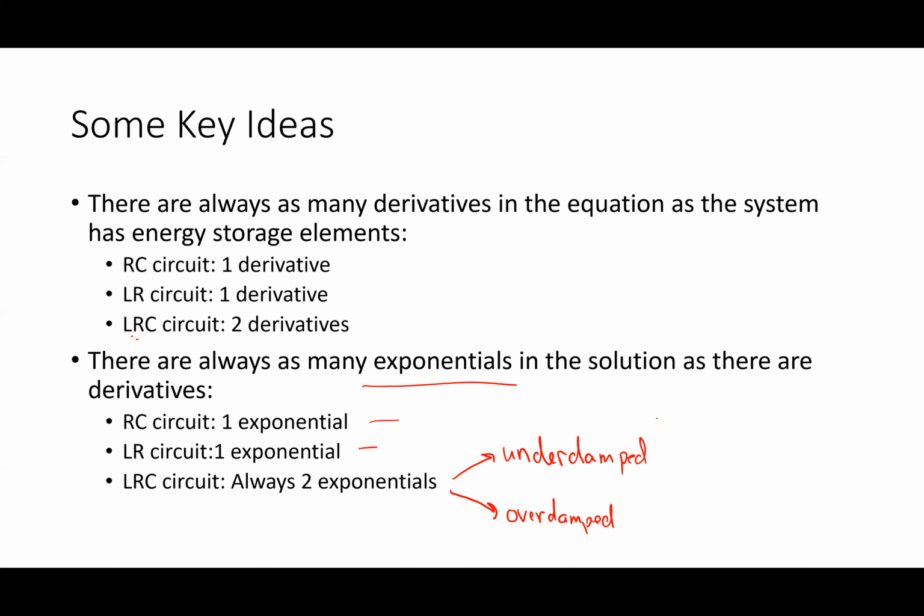Underdamped, basically, my roots are going to be complex. And what's it going to look like? It looks like a sine wave. Well, actually it looks like two exponentials. You're right, it's going to have a decaying sine wave, but there's going to be an e to the s1t and an e to the s2t in both cases.